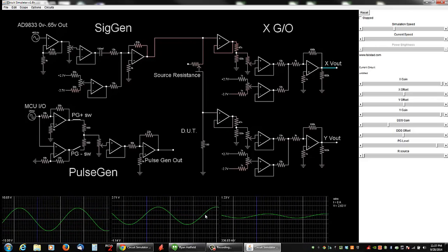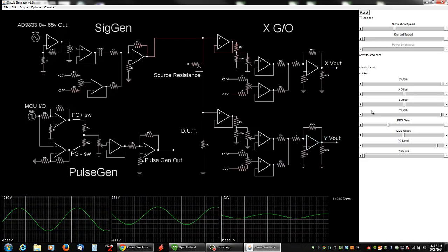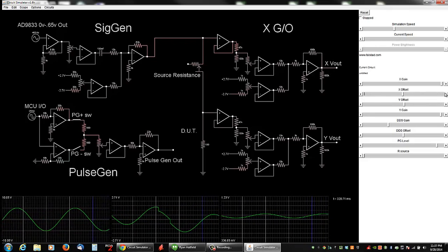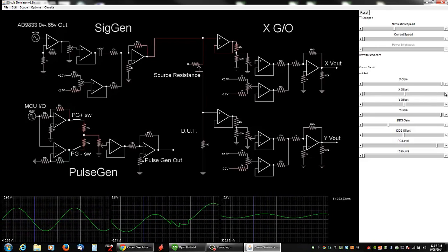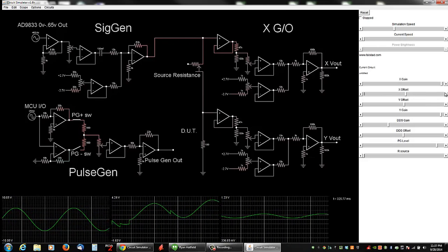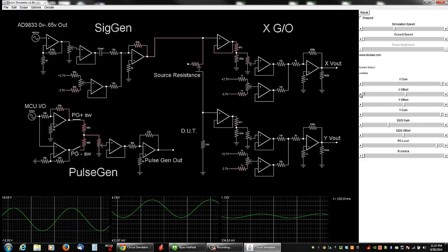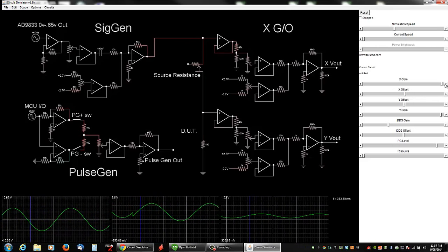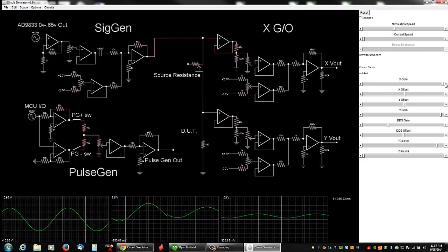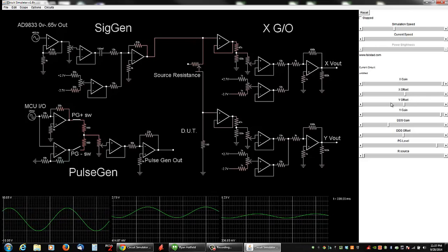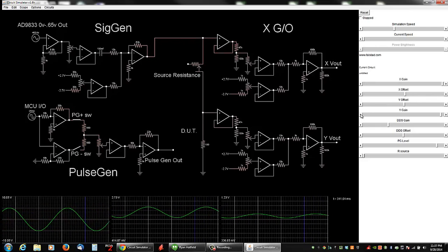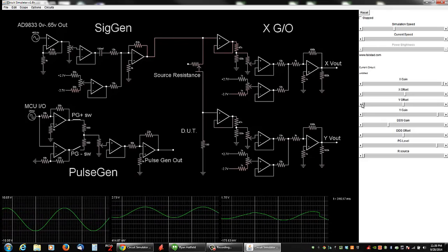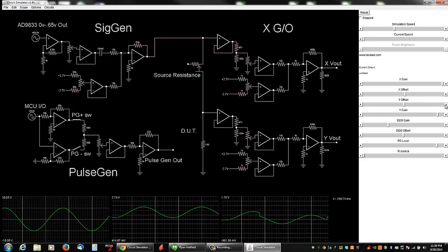Now in my case, I have to not put any negative voltage into the ADC, so I got to dial. Okay, that's the wrong way. Just got to set a few parameters here. Got to go between 0 to 3.3 volts in order to keep from smoking the ADCs. So that's good enough. Let's turn up a little bit more gain on the Y here. Offset it a little bit up.